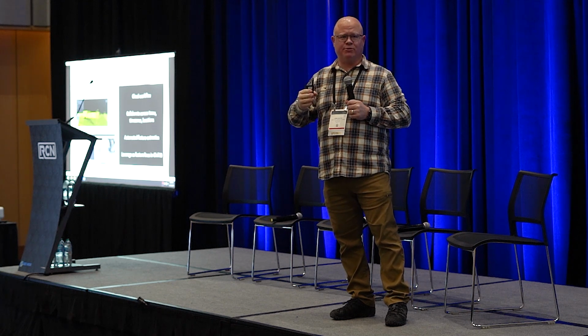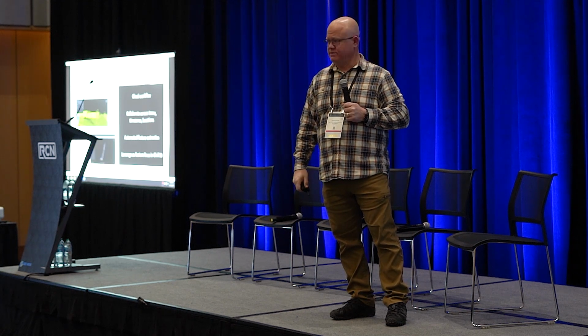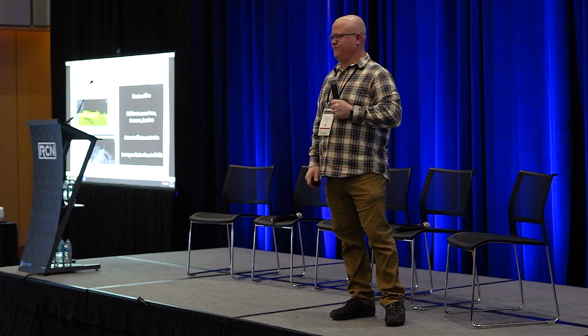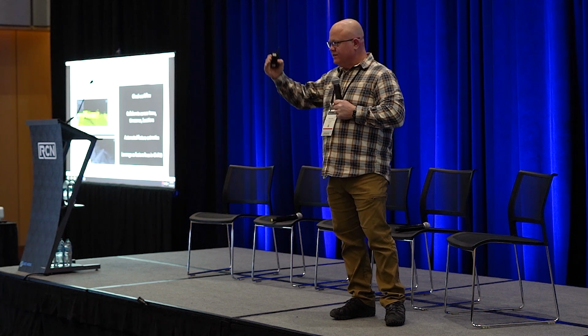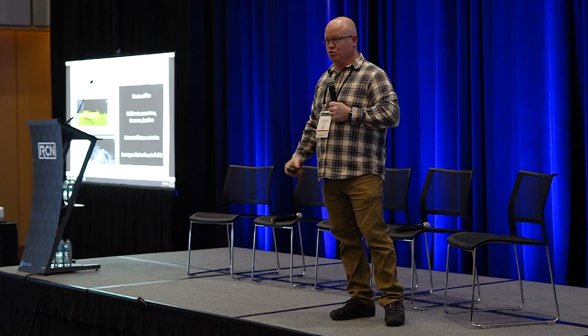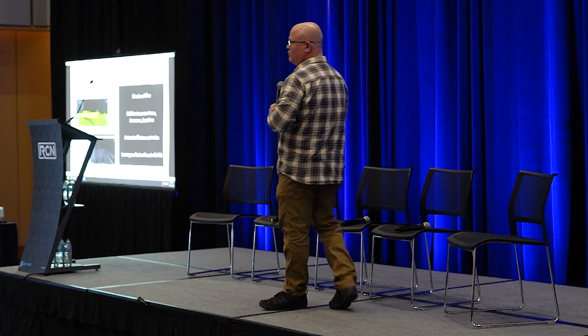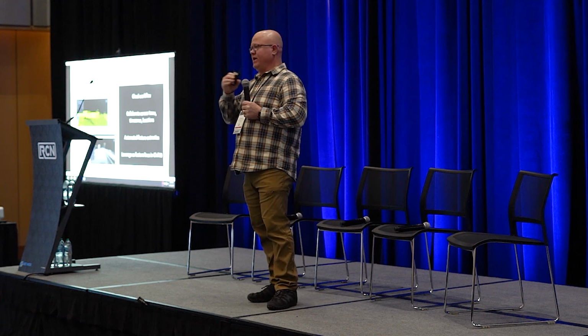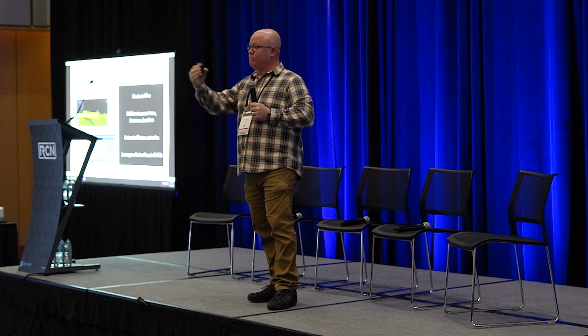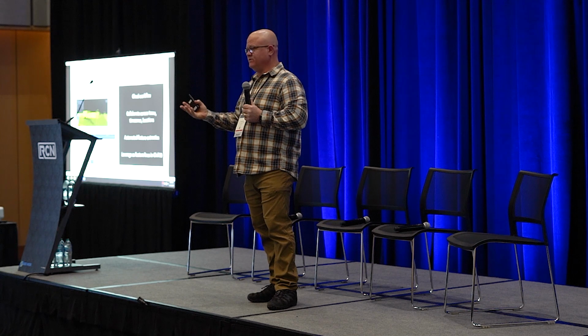So we can have it sample every 1/10 of a meter if you'd like. Now you're going to be sitting there for a little while watching it click off going around the curb, but you can do that. I did 3/4 of a mile of road, the curb and gutter, ran it to a barrier that was about another mile, and it took me about 15 minutes to capture all of that.